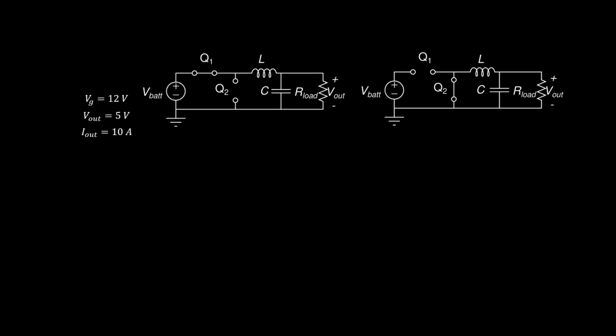So let's do it. We split it up. We draw the converter in two switching states. We're assuming steady state. And maybe a partial step that we can do before we write out the voltages and currents is to just specify what direction the voltages and currents are, right, in each switching state. And for this, you have to be consistent, right?